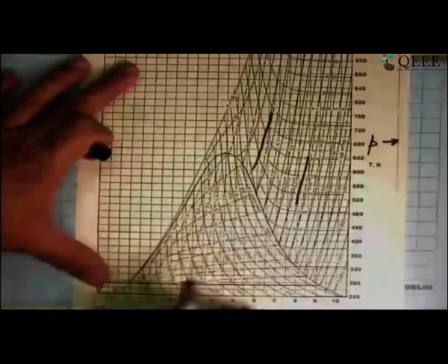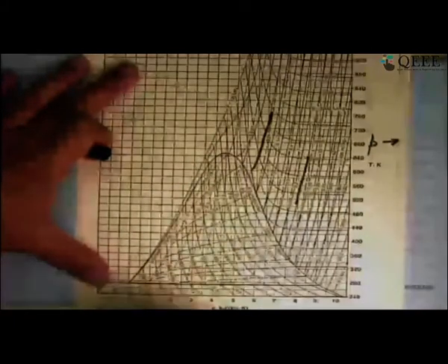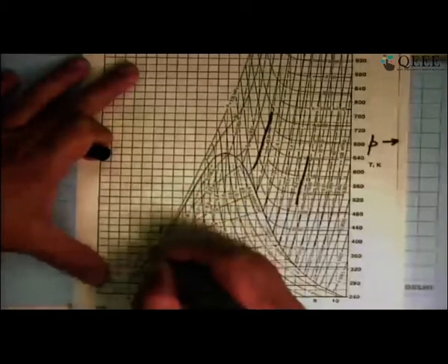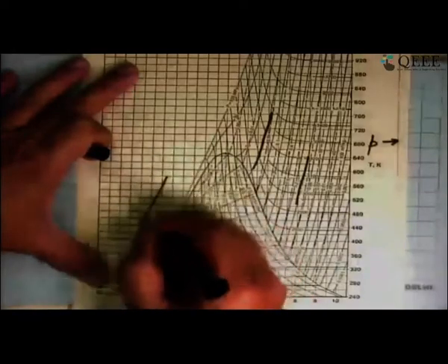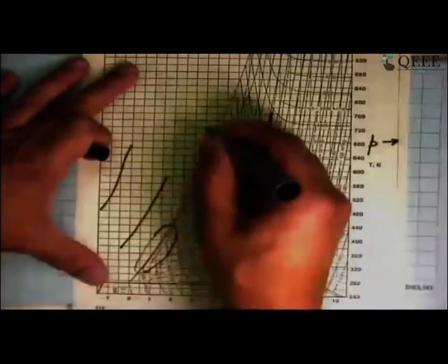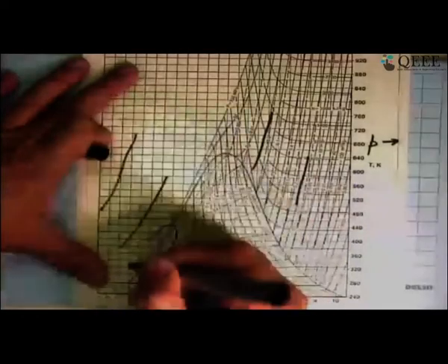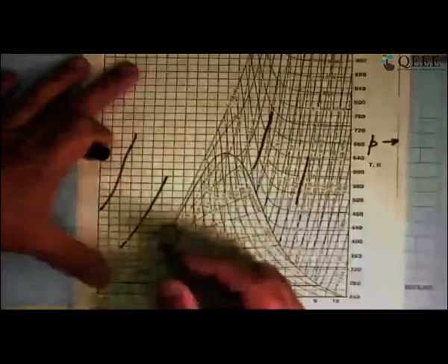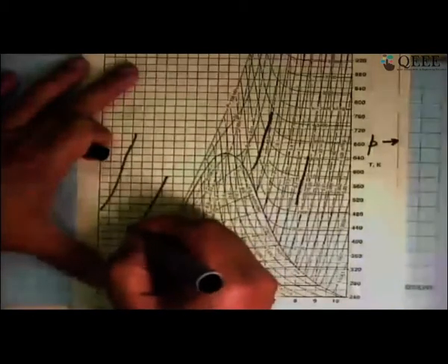The second case, which was the heating and cooling of a liquid, falls in this tiny little region which we cannot even see there. But if I blow up a little bit of this part, this is the saturation curve and this is the line over here, which is the 100 bar, then the heating processes which follow constant pressure will follow pretty much like this.